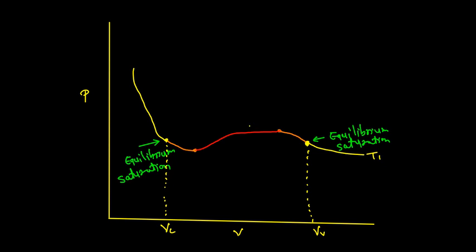Now I increase the temperature, but as I increase the temperature, what will happen is these two points will come closer, and the behavior of the system beyond this must continue, right? And similarly here you will have where the system just attains the limit of stability, and here you have the unstable region.